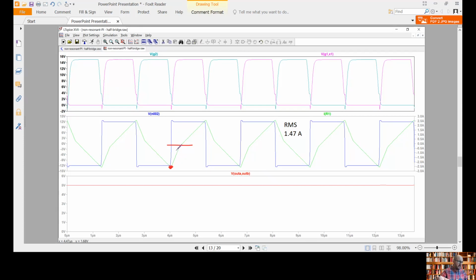In this first interval, when we are applying this voltage at the gate of the top transistor, it is conducting the antiparallel diode of the transistor. Then the current naturally goes positive and goes through the channel of the transistor. So we are having here zero voltage switching. And also with the dead time that we are providing between these two gate signals,